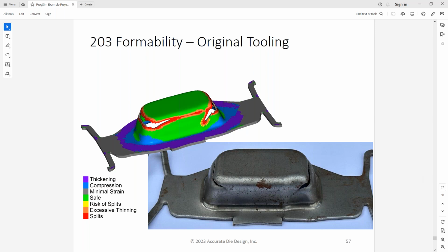But a lot of times when a part starts to fail, very little simulation software out there probably shows you exactly where the failure is. They'll certainly show where the thinning is. The ones that are right will show you where the thinning starts, but exactly what the crack looks like, this one might always be a flyer, because once cracking starts, it's hard to determine where it goes, and it's really not so important to see where it goes. It's important to know when it starts.